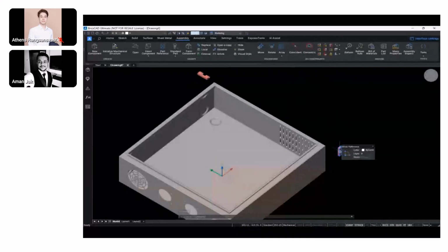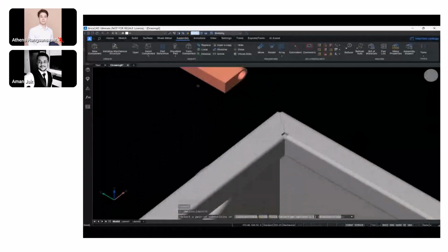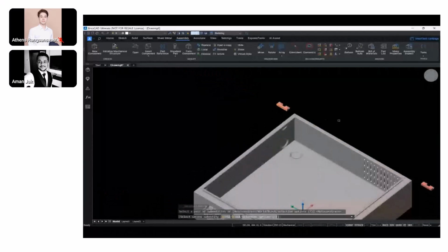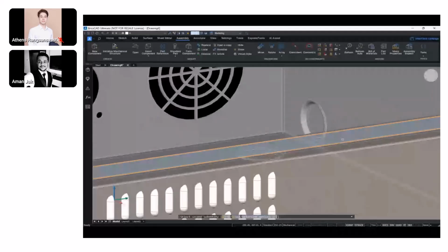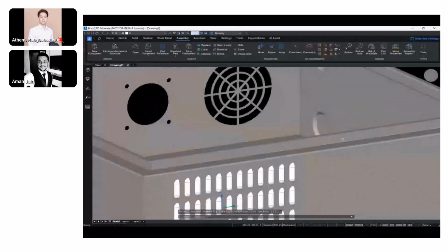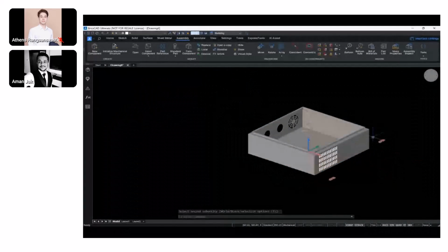Any change in the hinge 2 that we had in the door would be reflected in the subassembly as well as the main assembly. Okay, so it's cascading down. Let's say if there's a change in the child file, all the parent files would accommodate those changes to those parts as well. Okay, so here is where we are applying constraints to these hinges.